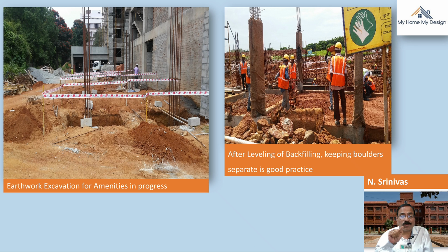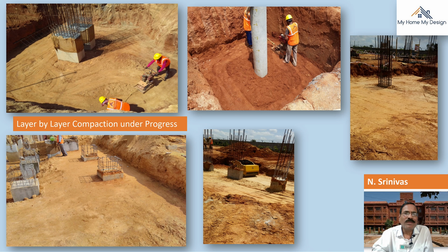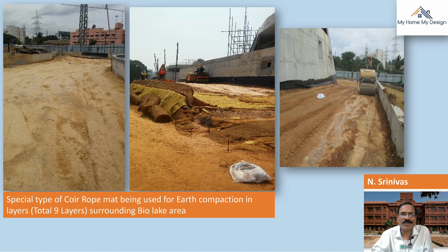So these photographs clearly indicate all these boulders more than 4 inches, more than 6 inches, everything has to be discarded and not to be used for the backfilling. So now it is clear. See again, layer by layer compaction under process. This is the systematic way the compaction has to be done. These photographs clearly indicate.